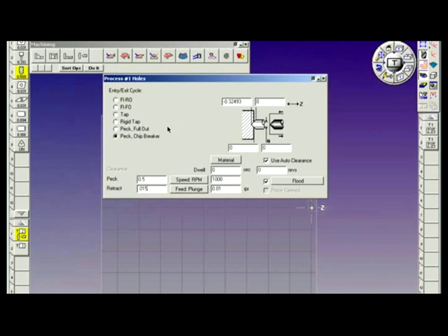In this particular case, we're using a center drill. So I'm going to use a feed in, rapid out with a dwell of 0.25. We're going to dwell for a quarter second at the bottom of the cut. We can also specify a dwell by revolutions as a time increment or by number of revolutions, maybe 5 revs. It's 0.3 of a second. That ensures I get a nice clean surface so that my drill enters straight in.